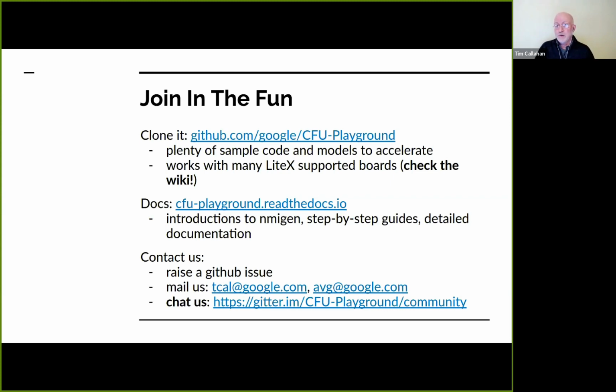I've been talking to a faculty member at a university, and he was very interested in adding the RISC-V vector extension as a CFU, that is, using the CFU interface. He had to bend things a little bit because there are certain aspects of vector instructions that go around the limitations that I put on the CFU, specifically accessing the scalar register file. But it is certainly feasible. Actually, I think there was also a European project with Core 5 that used their coprocessor interface to implement the vector instruction.